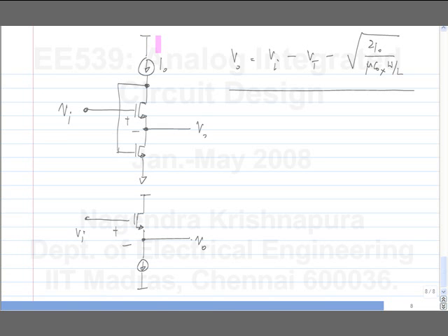Okay, what he explained and also what he said earlier was that looking in here, it's infinite impedance because it's a common gate amplifier which is open circuited at the drain. That's the logic. Yeah. And looking in here, it's infinite impedance because it's a current source. Is that correct?